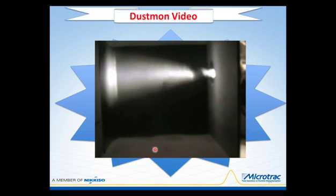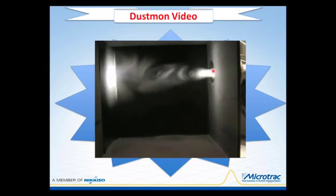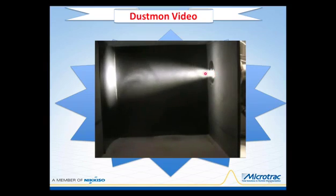At the bottom of the bin is the coarser particles that have not been involved with formation of the dust plume. And you can see the light, which again is an LED, it's a white light, that illuminates the particles. And by means of light obscuration, the dust retards the light reaching the detector system that's located over on the left side of the instrument.